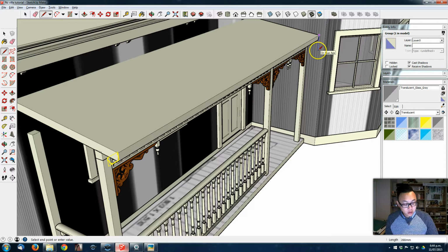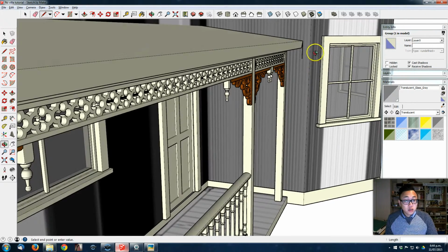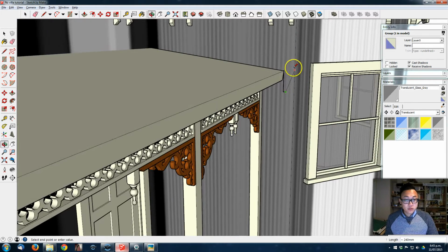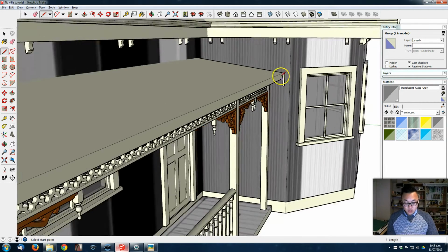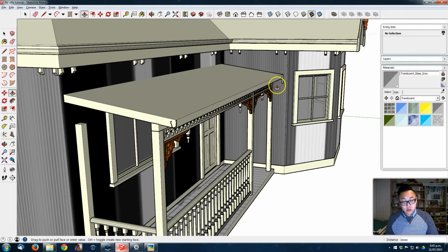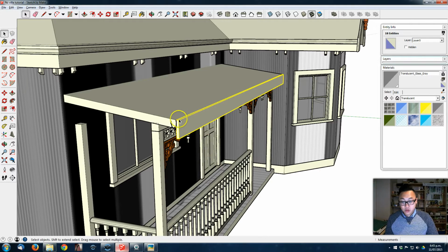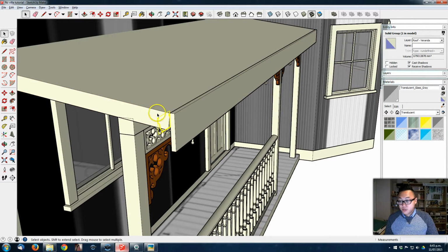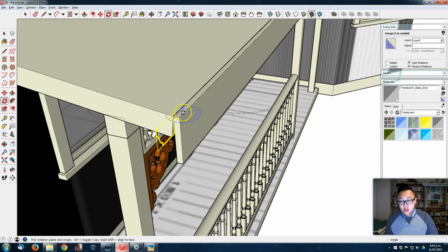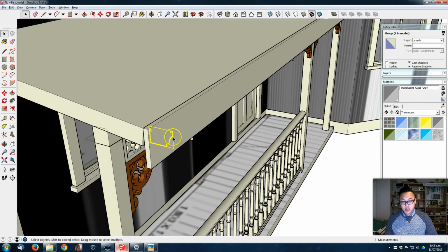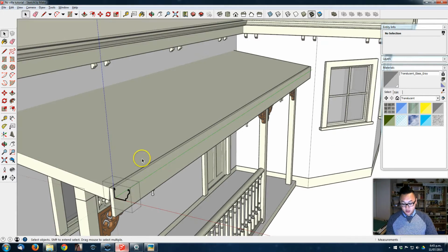So from this point to 230, or maybe a bit smaller, let's say 200, thickness of 25, and then I'm going to extrude it. Triple click, make it as a group, take the gutter object and rotate it into place. Double click to get inside and extrude it.